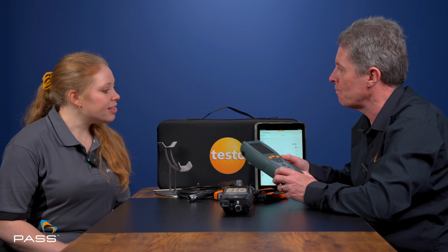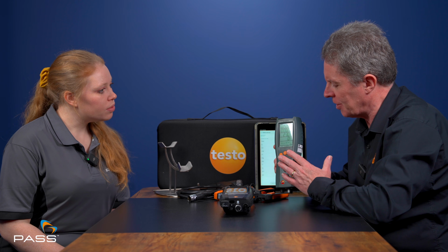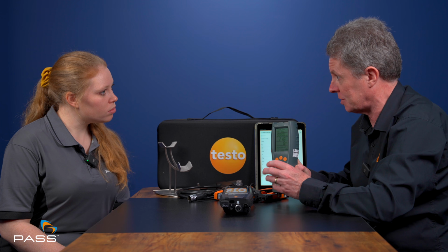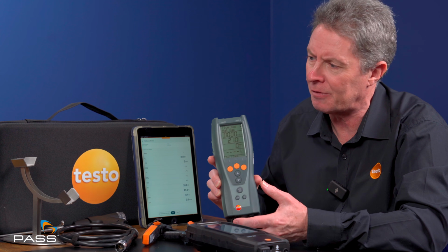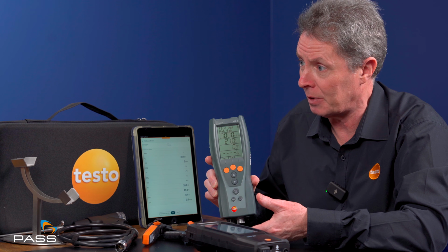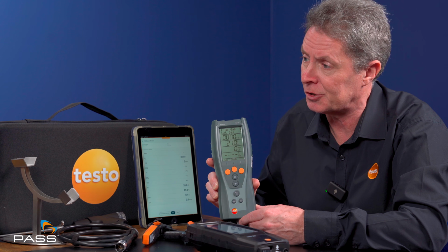Okay. And would you say that's an entry-level model or a mid-range? It's mid-range, yeah. We do have a device in our range that sits below this. It's limited in functionality. It can only do flue gas combustion readings. This really is the first point where you've got the ability to do these other tests that are required. The tightness and let-by is a key one, and also the flow and return temperature is something that people often want to do with the boiler as well.